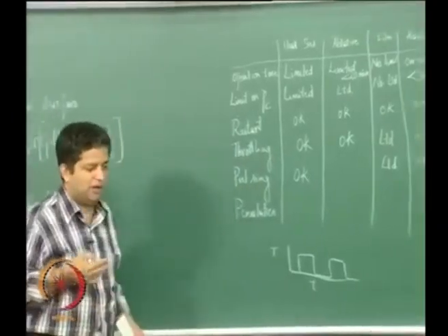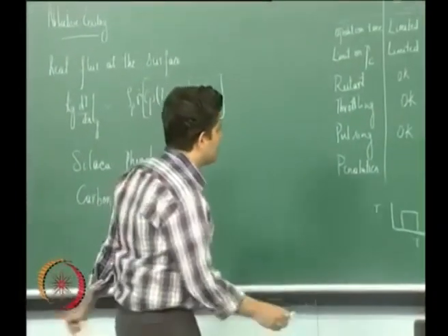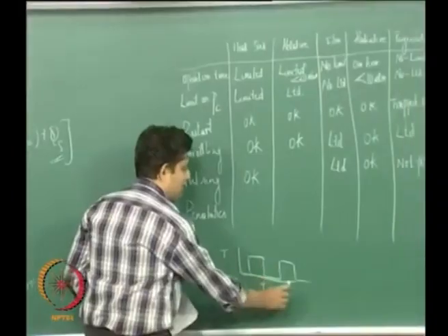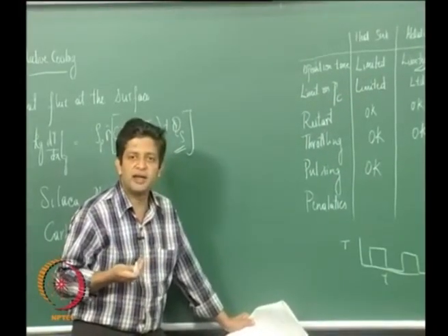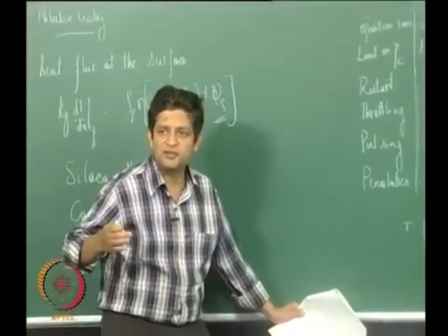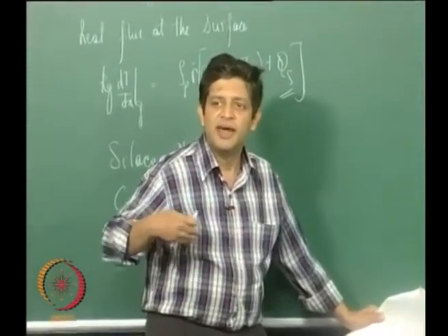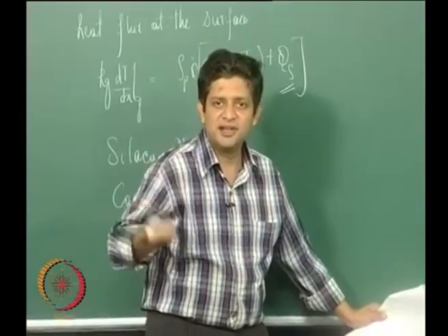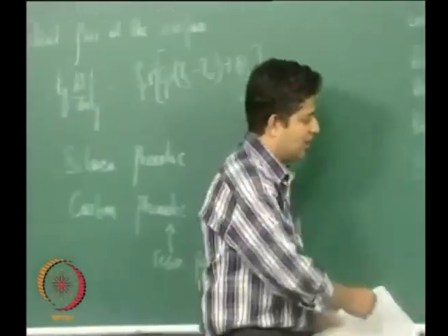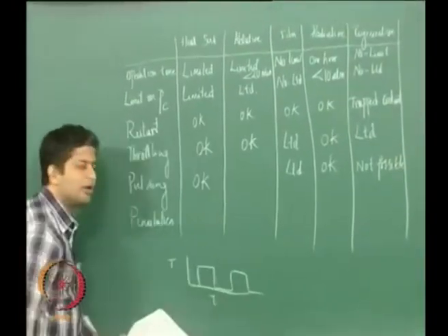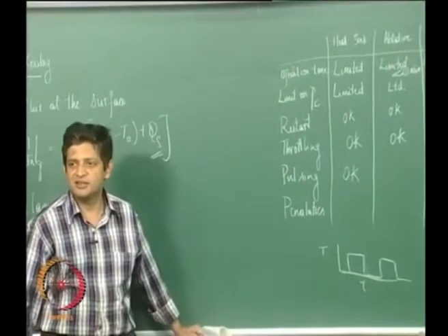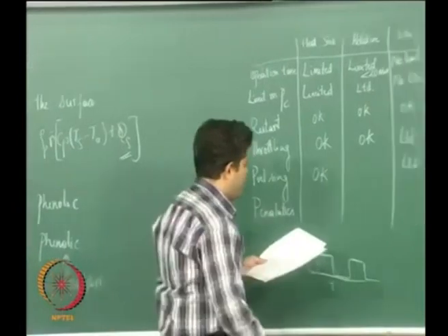If you are wanting to have a very sharp cutoff, and you have an ablative material that chars and erodes, there is some amount of gases that are going to be released. So the thrust cutoff will not be as sharp, and you could have a residual thrust. Okay.